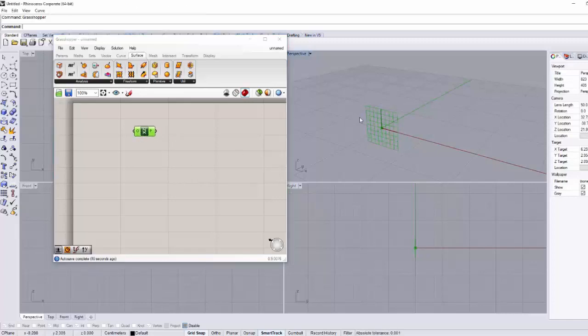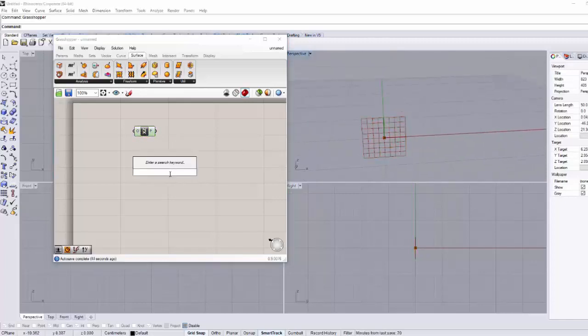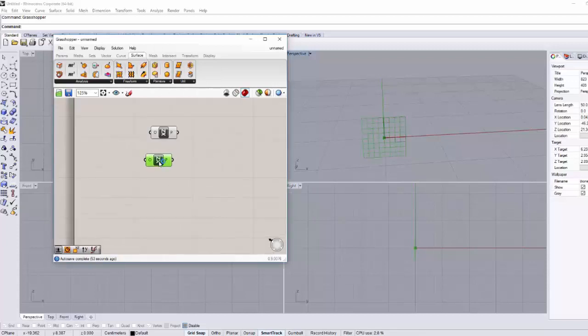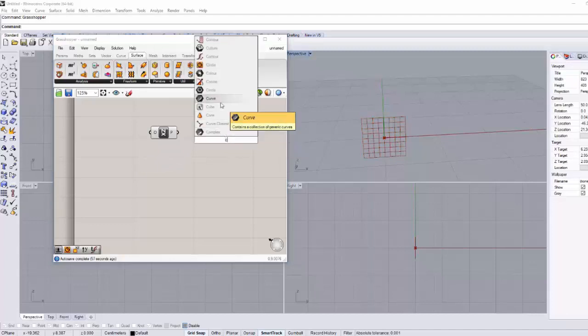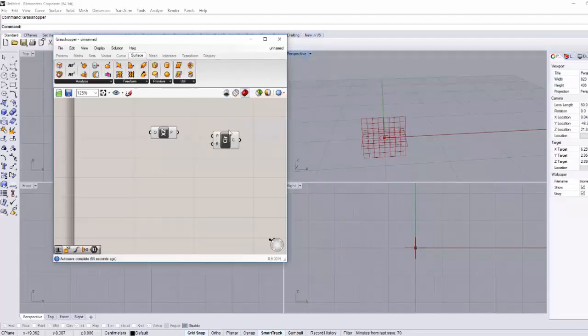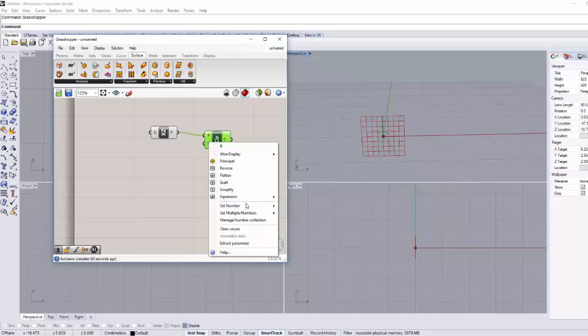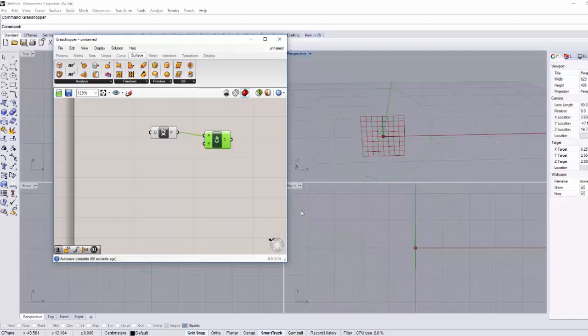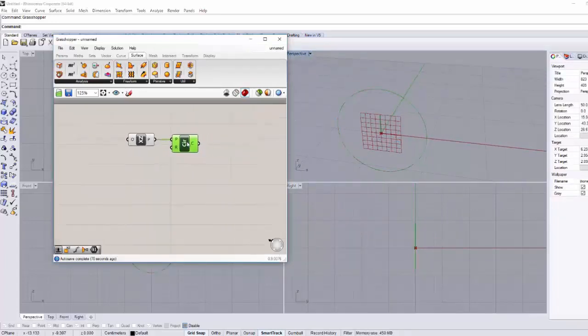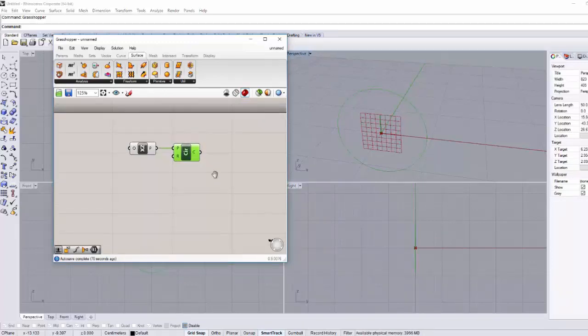We'll start with the XZ plane, so 2 times, every time. It's just 2 times on the screen, XZ. That's the plane where we're going to draw a circle. You can check the diameter, the radius. You can calculate the radius, but as far as I'm concerned, I'm always using the radius of 9.1 millimeters, which corresponds to some 8.6 something in the EU size chart. I just remember it's 9.1, and that's always how I do it.